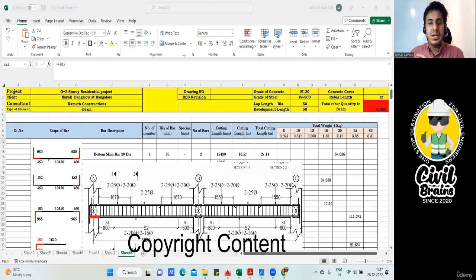Then what will be my horizontal length? It will be whatever my column dimension is, and from there you deduct one cover for the column. I've written 500, that is the size of my column, and from this I've deducted the 40 mm cover. So 500 minus 40. Got it? That is why I'm getting 460.